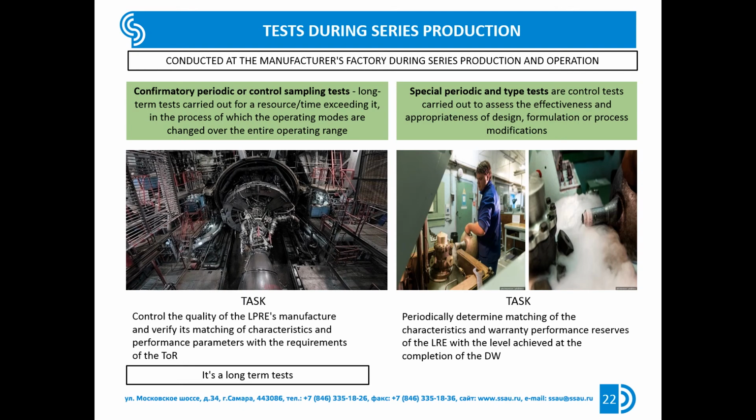Special periodic tests are intended to periodically determine whether the performance and warranty serviceability reserves of the LPRE are at the level achieved at the completion of the development work. In addition, these tests are used to check the stability of the technological process. Special periodic tests are conducted in an extended range of parameters relative to the operating range in order to verify the stability of production.